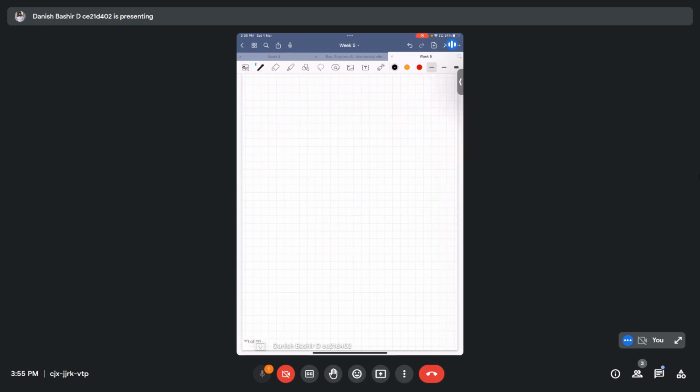We have to look for the particular integral. Particular integral x of t, subscript p, will be equal to, in the notation I showed you earlier, 1 by (d square plus p square) times p square x static naught sin omega t.